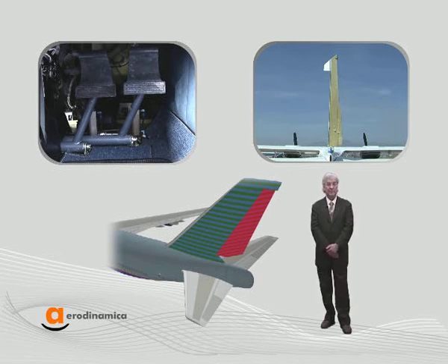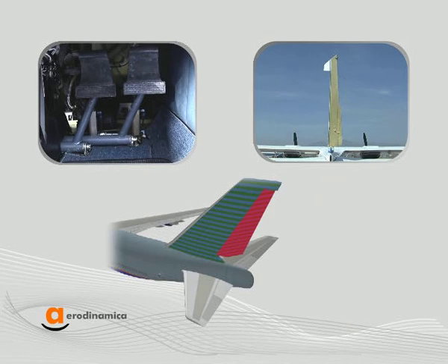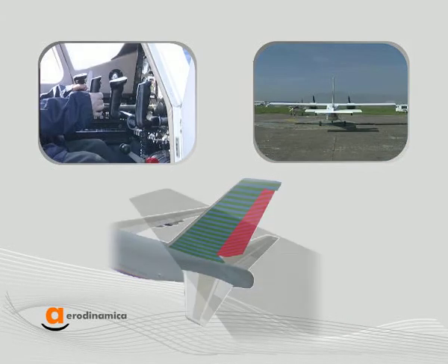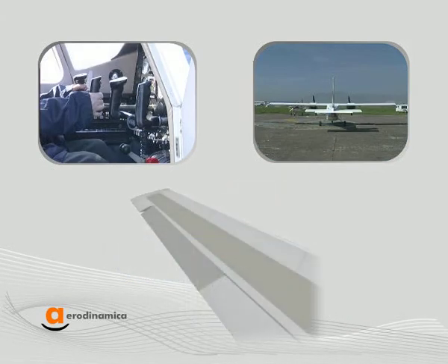So, do we use the rudder to change the direction of the airplane? Yes. The airplane changes direction through the turn maneuvers, performed by using the ailerons. The ailerons move simultaneously and in an unsymmetrical way. This means that when the aileron of a half wing turns down, the aileron on the other half turns up. Let's see how the pilot makes them work.